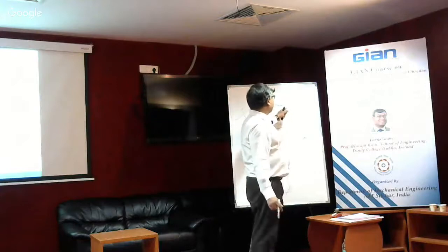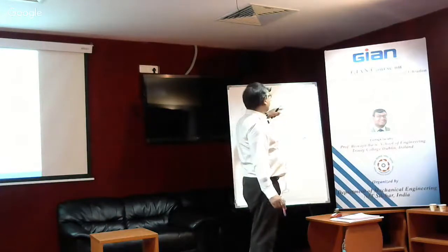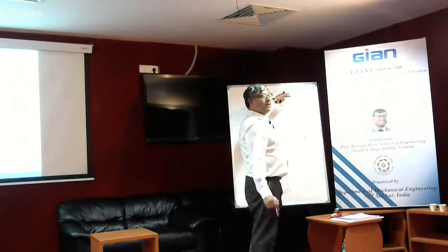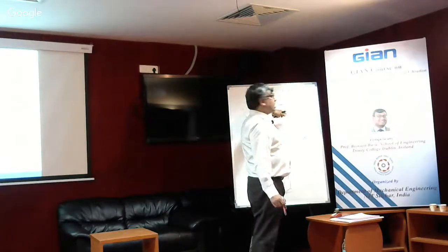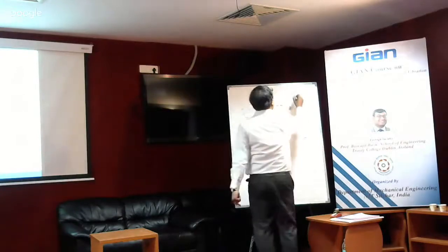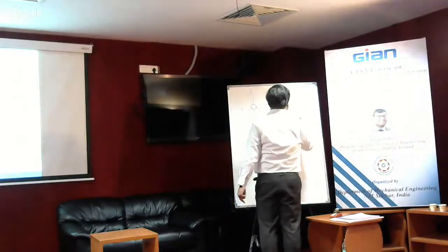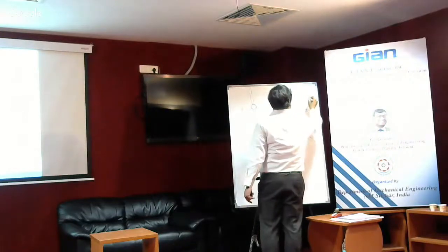So here, the lift actually is caused because of the pressure difference between the top and the bottom. There's a pressure here, there's a pressure here. And the pressure normally at the top is lower. So pressure at the upper face, PU, and pressure at the lower face, PL. And pressure at the upper face is actually less than pressure at the lower face.